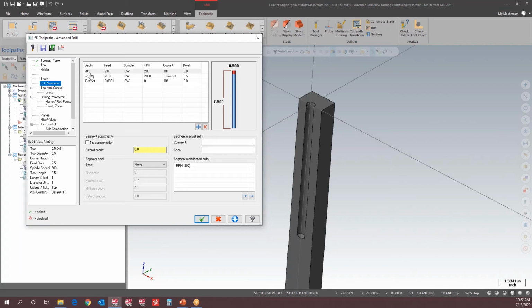This first move, I want to go into my part a half-inch deep with a slow feed rate and a really low RPM. My tool's barely spinning because this is a 10-inch long drill. If I crank up my RPM to what it's asking me to cut at, the drill might whip. If I turn my through spindle coolant on, the tool still might whip. So I have everything turned off until I get to a half inch deep, because I'm assuming I've already drilled this hole a couple inches deep or something like that.